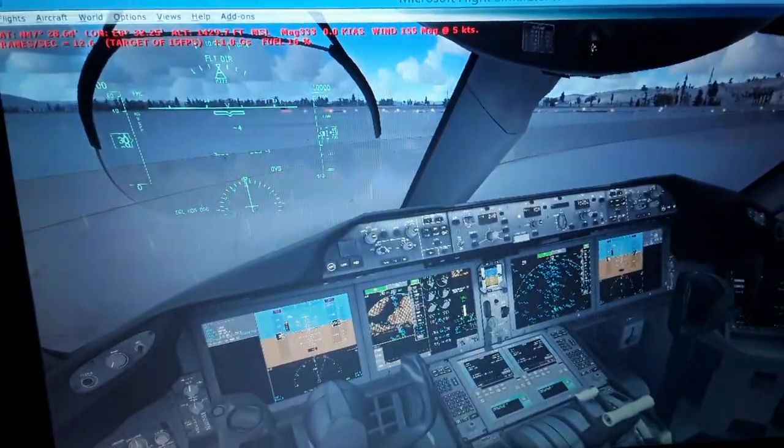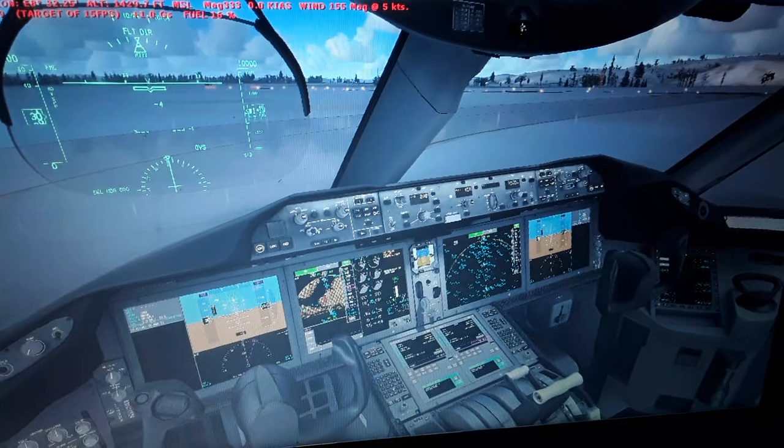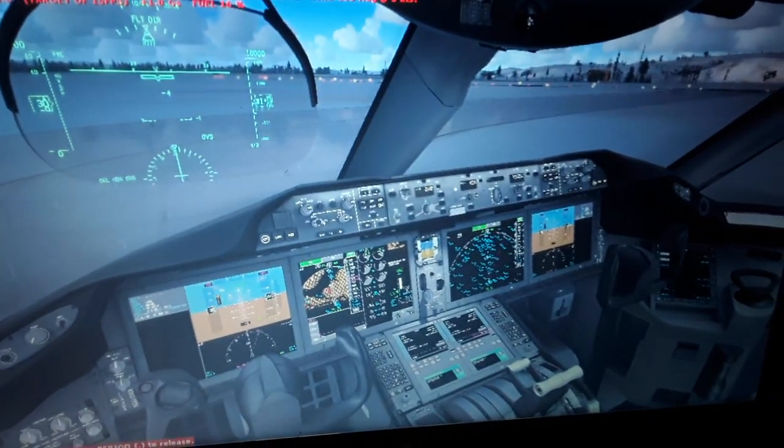So we're going to have the ILS localizer, the instrument landing system of the airport. You're gonna see how we're gonna use it in the primary flight display and the autopilot flight director system panel over here, the navigation display also. So you're gonna see the navigation instruments of the aircraft, and so we have in the primary flight display also the ILS localizer crossbars, the flight director crossbars for manual guidance of the aircraft, and the autopilot crossbars for automatic guidance of the aircraft.